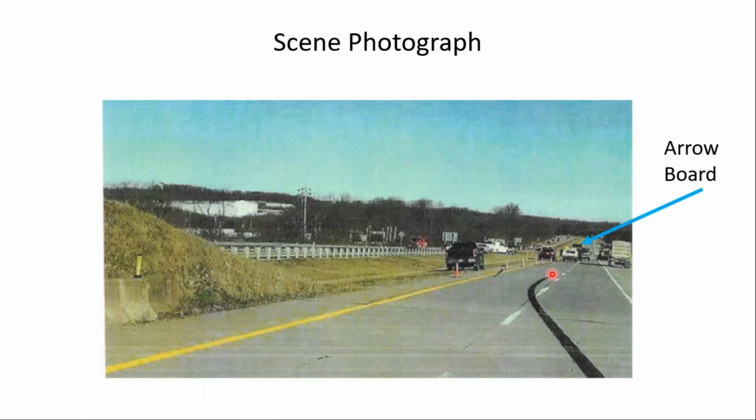And interestingly, and this is not unusual that this sort of thing happens, this was not the tire mark from the truck driver, or actually from anybody involved in this incident. This apparently was from a previous incident. This mark here in the distance next to that black pickup truck was apparently made by the dump truck driver as he had braked and was swerving into the median. But notice the arrow board is back here rather than at the start of the taper.